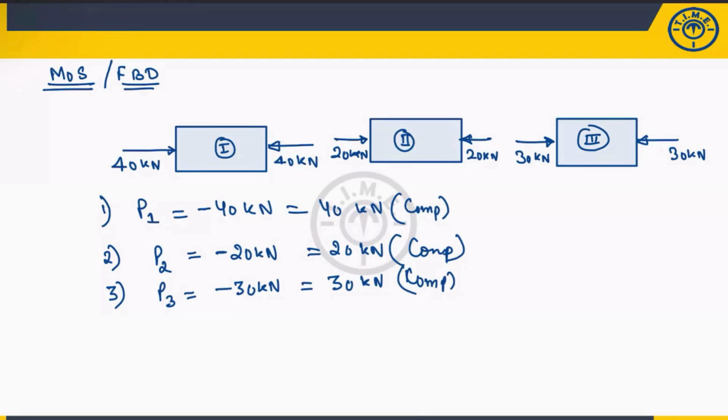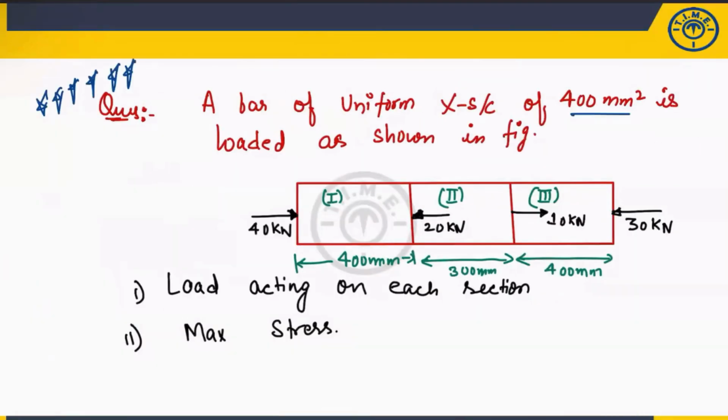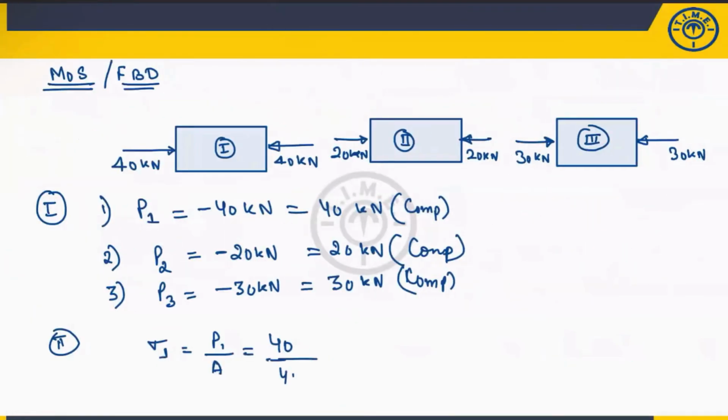Once you know the force value, can you calculate the stress value? Stress value is simple. How will you calculate stress? Force per unit area. What is force? 40. What is the area? Let me check. Yeah, 400 millimeter square.